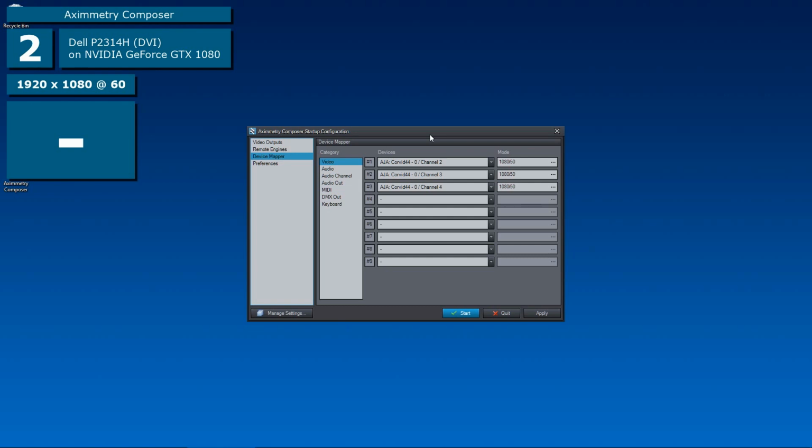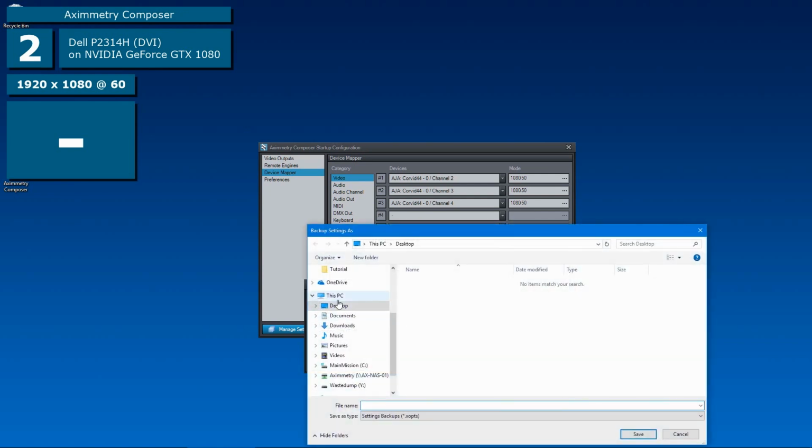We should mention here that our settings can be saved and therefore these can be loaded in later if we want to perform changes between configuration settings or if we want to secure ourselves against system accidents as a backup measure. We can do this by clicking on the Manage Settings button. We will find many different groups of settings here. Among these, we have only dealt with the one called Startup. Nevertheless, we leave all these groups on by leaving their boxes ticked. Now we click on the Backup button and save it on the desktop as a file called test1, like this.